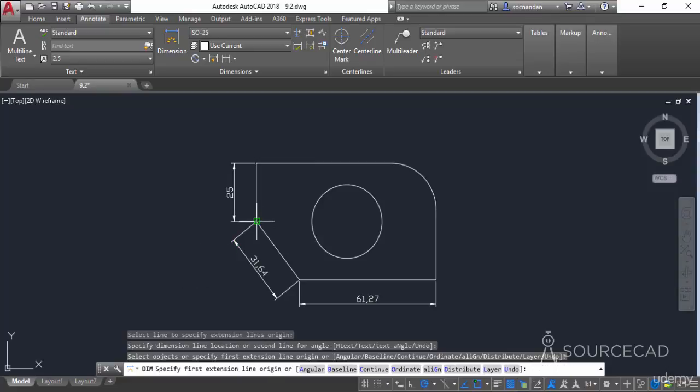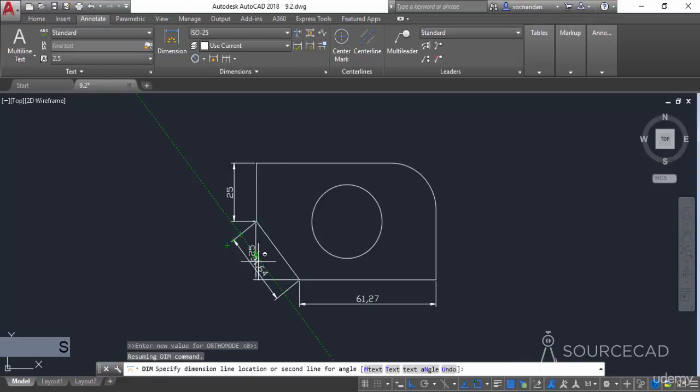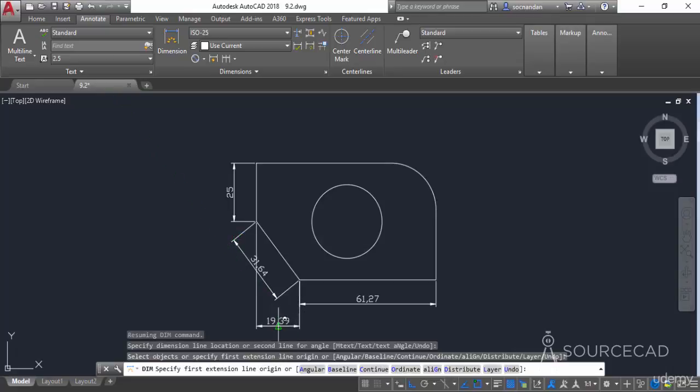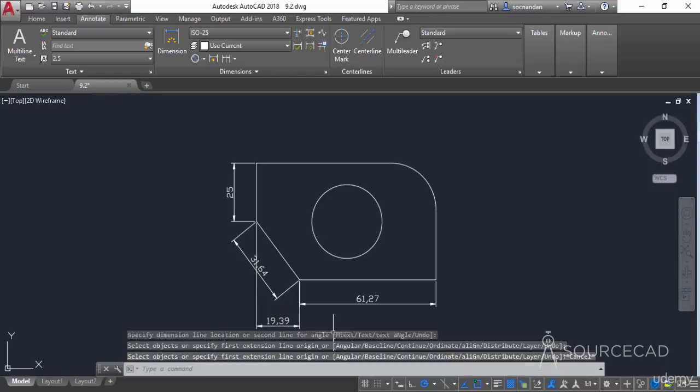For that, simply click on the first point, click on the second point, and now press and hold the shift key, and you'll notice that your dimension will change into linear dimensions. In this case, since I'm moving my cursor in this vertical direction, it's making this vertical, and if I move it downwards, it will make this simple horizontal dimension. So you can select any of these dimensions simply by pressing the shift key. I'll click here and we have this horizontal dimension also. Now I'll press the escape key and I'll remove some of these dimensions.